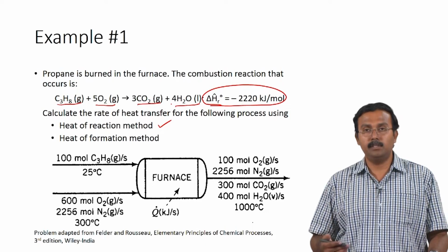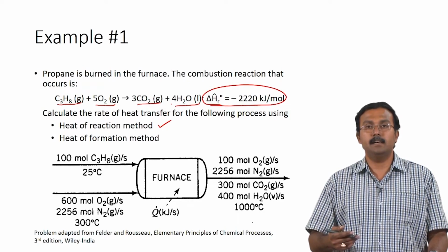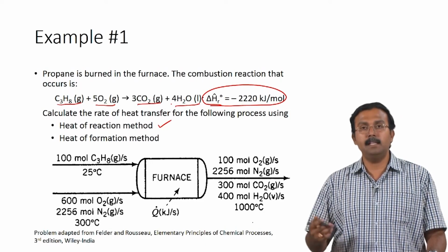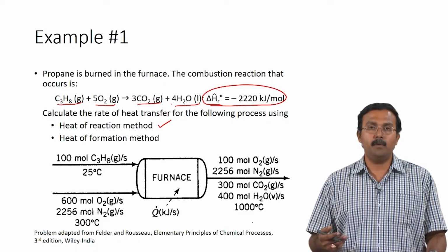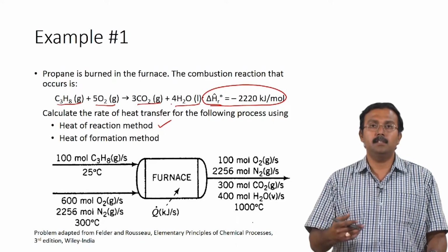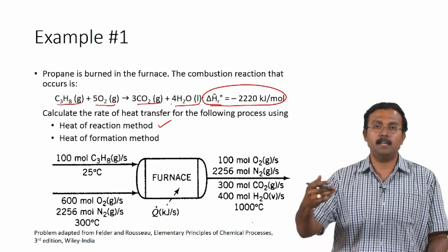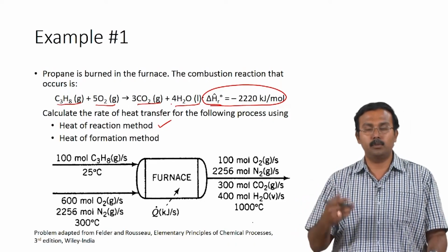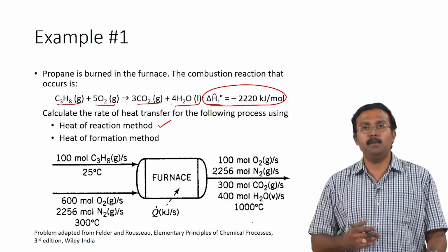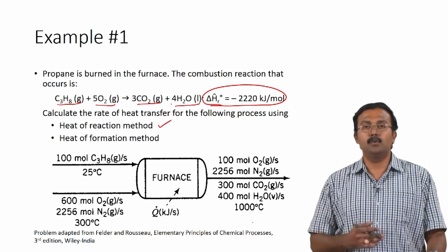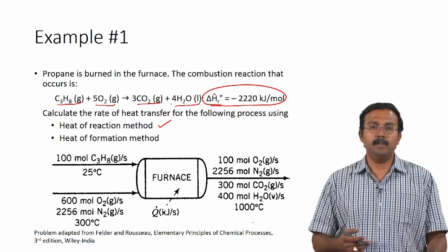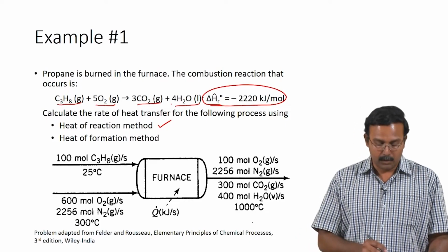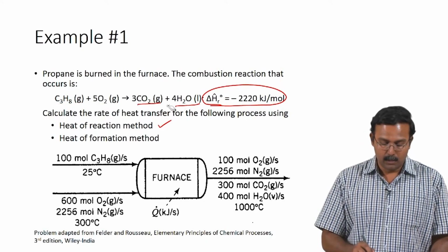Then you would be building the enthalpy table which accounts for the heat of formation as part of the step where, from the reference state of carbon and oxygen, it goes to carbon dioxide, and then the next step would be the heating. With this kind of process you account for the heat of reaction in an implicit way.